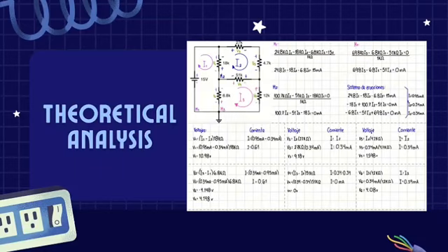We did the analysis with the short method, which is the sum of all resistances in the mesh multiplied by the current of that mesh, minus the resistance that is shared with another mesh multiplied by the current of the mesh with which it is shared, and so on until there are no more shared resistances. Then equalize to the number of volts that mesh has. In case the voltage is not available, it equals 0, and then all this is divided by 1 kilo to obtain the units, which are in milliamperes.